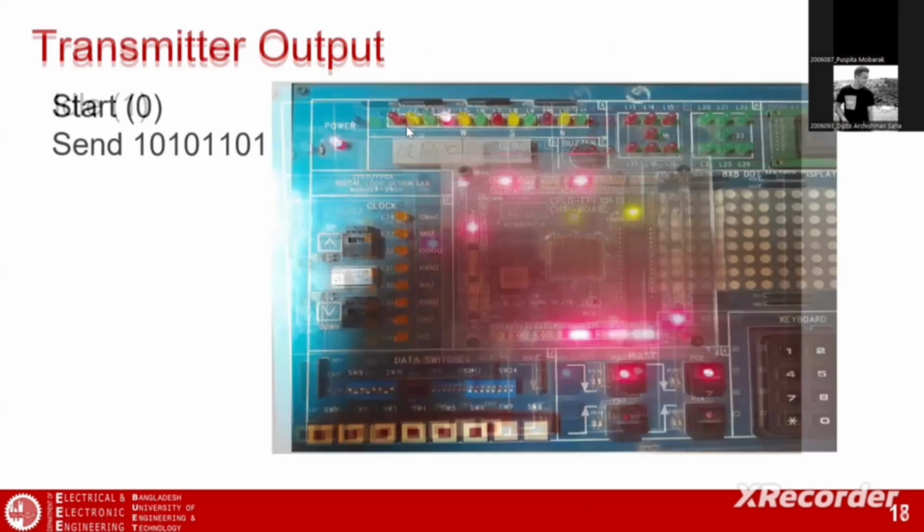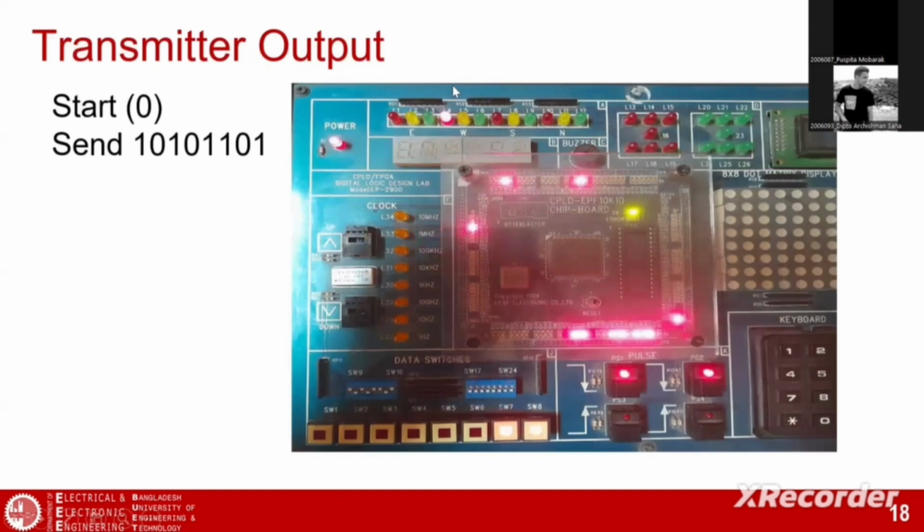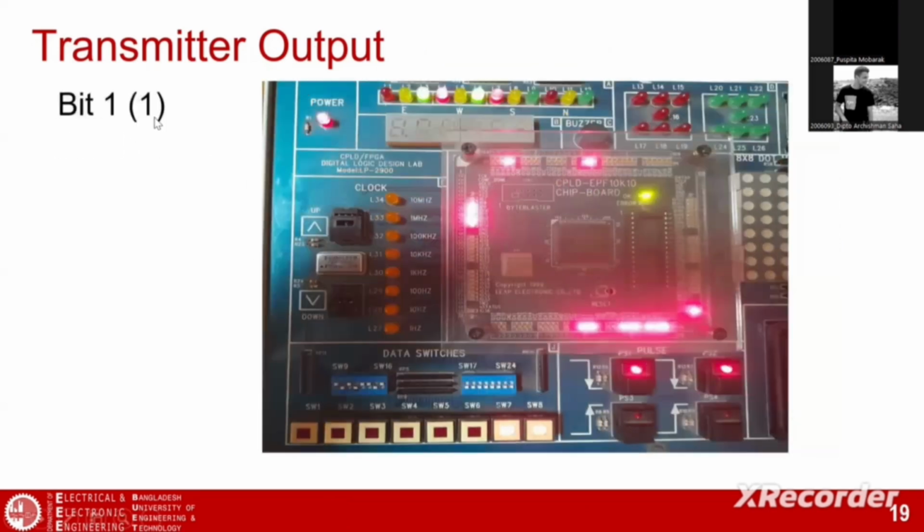Now the start bit, L7 has become 0, and L4 has become 1. That means the system is active. Now bit 1 is sent, bit 1 is 1, so L7 equal to 1. L6 is also equal to 1 because the parity is now odd. And L4 is equal to 1 means the system is active. And L3 is indicating 1, and L2, L1 are indicating 0. That means L1, L2, L3 is equal to 0, 0, 1, which indicates the bit index.